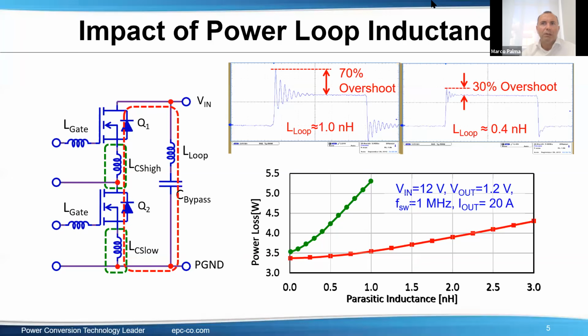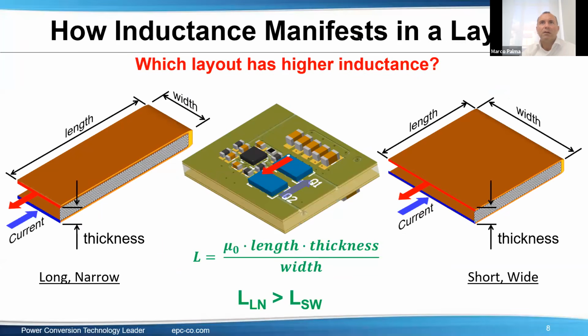If we put it on the pad, then it's better doing what we call via in pad plated over. Okay. So if you do it like this, as in the picture, if you look here, the via in reality is not really on the pad, it is on the trace.